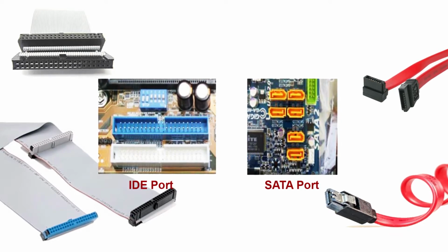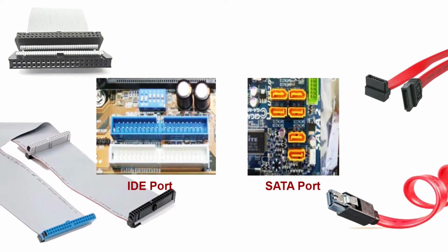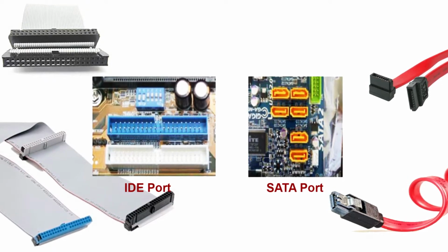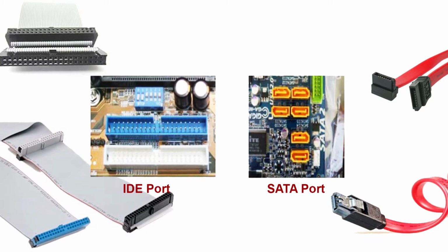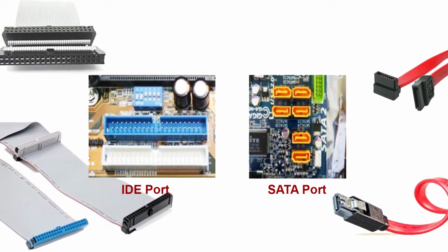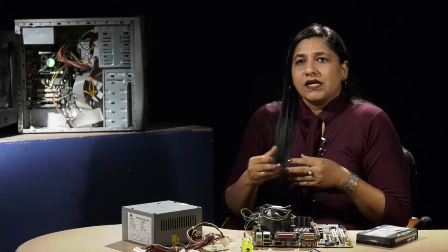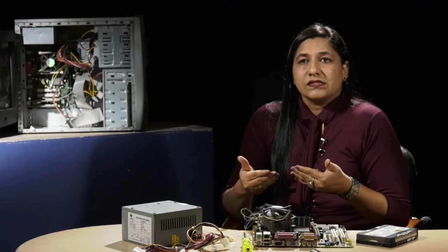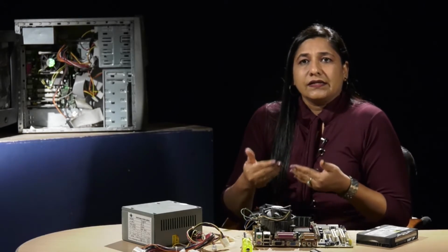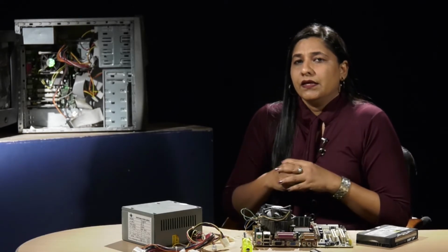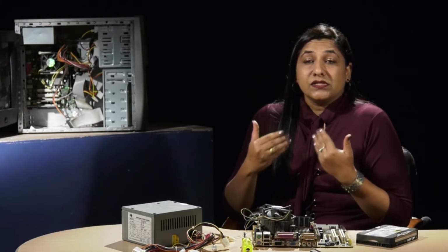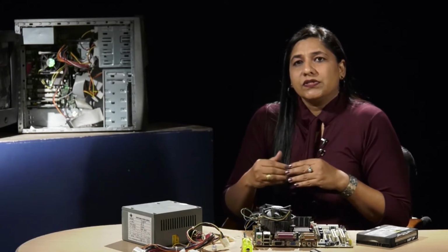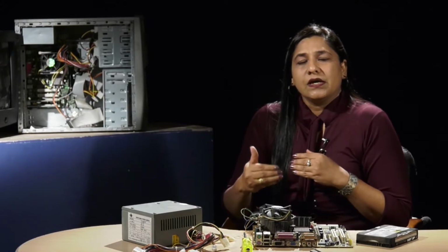This IDE interface is somewhat outdated now, and has been replaced by the smaller and much faster SATA interface, that is Serial Advanced Technology Attachment or Serial ATA. SATA is now the new standard in modern computers, which is much faster in transfer of data than its counterpart IDE, being able to attain a speed of up to 600 megabytes per second and more, as opposed to the IDE interface which can reach a maximum of 133 megabytes per second.